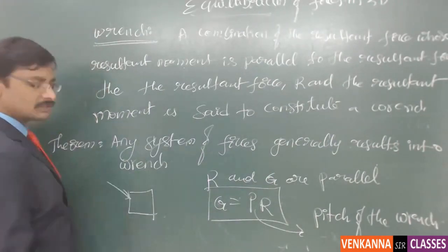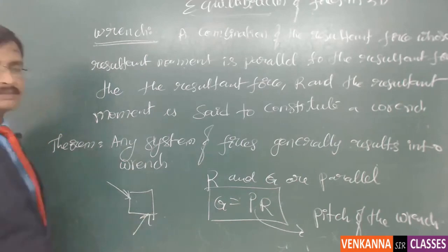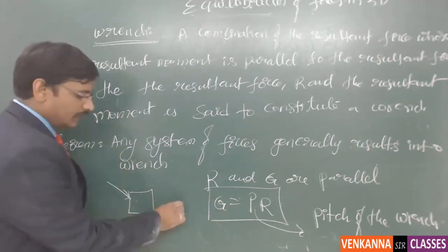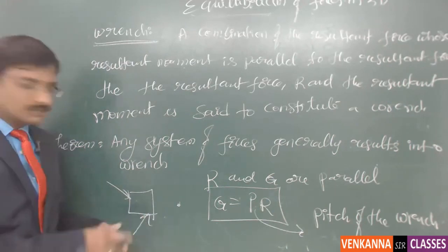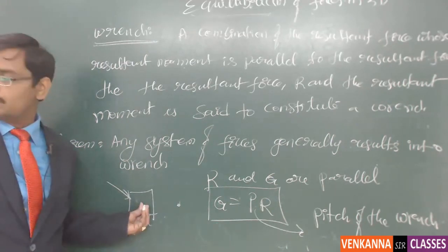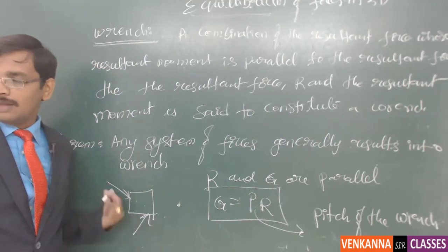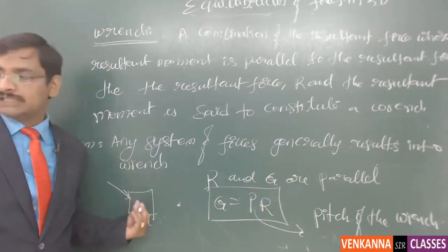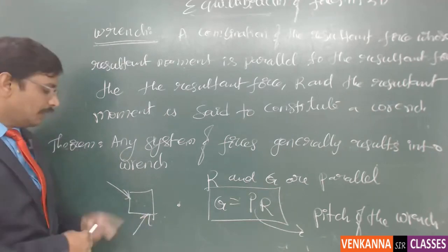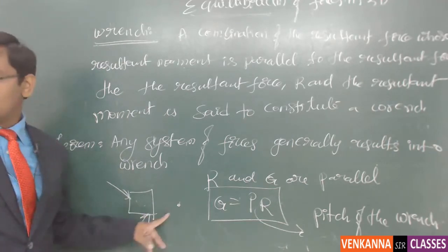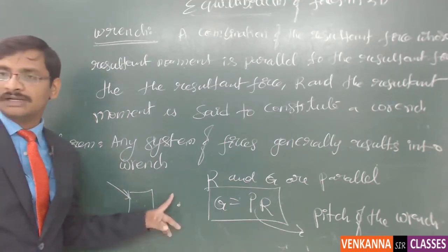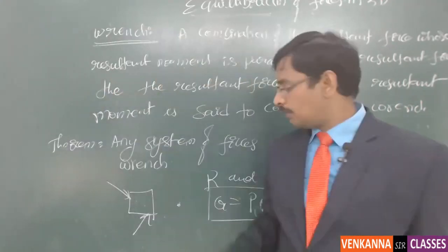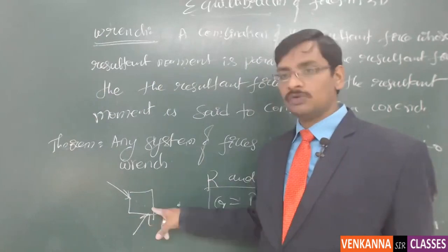See this. Suppose there is a force like this and a force like this. Whatever the base point you select, the resultant torque always has a direction perpendicular to this board, which is normal to all the forces. So the resultant moment direction is always the same. Also, the resultant force magnitude and direction are always the same in case of coplanar forces.